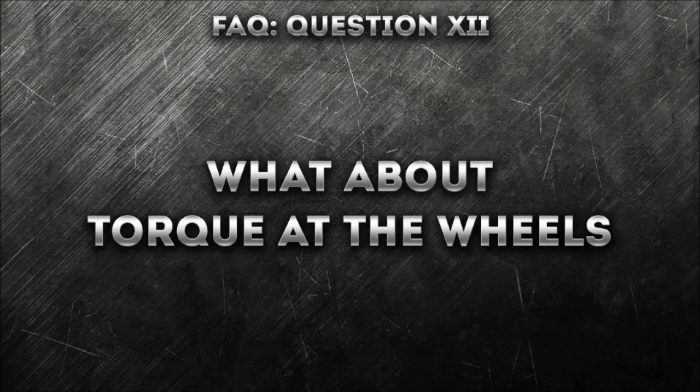Hence, torque at the wheels is not necessarily a good measure to use unless a lot of relevant surrounding data is known. With that disclaimer in mind, yes, if you know torque at the wheels, the grip and slip angle of the tires, the speed of the car and the various resistances and friction, torque at the wheels lets you calculate the forces which accelerate the car directly.